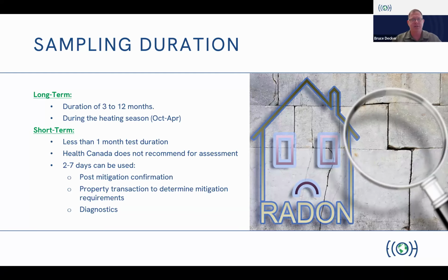The other thing to consider too is there's frost in the ground. So that radon that would have naturally escaped through the ground tends to concentrate a bit underneath the frost. That's one of the reasons why we tend to see higher readings in the winter months. But that 200 becquerels is your average annual exposure. So if you want to get as accurate as possible, you test for 12 months, and that's what you can compare to. But that can be a little unrealistic for a lot of commercial applications.